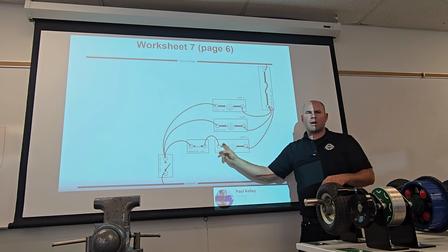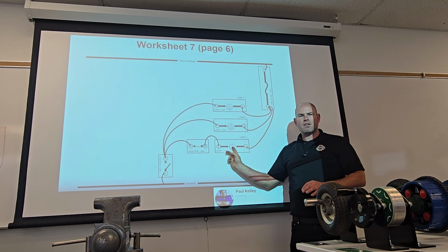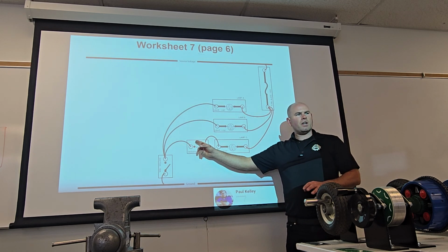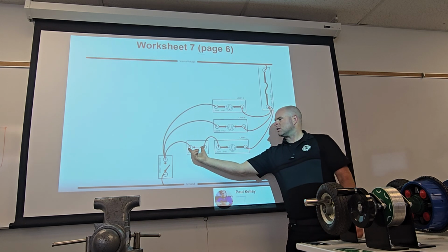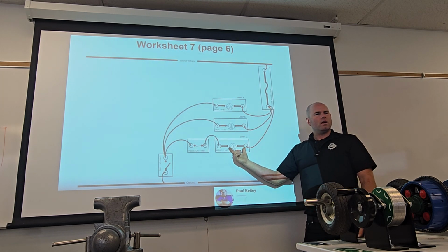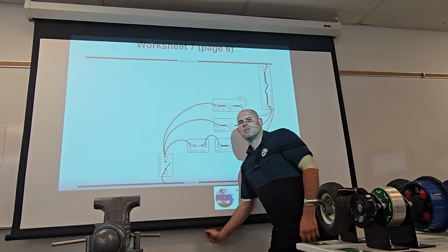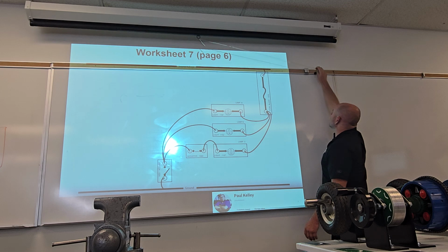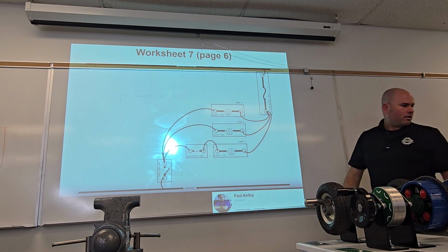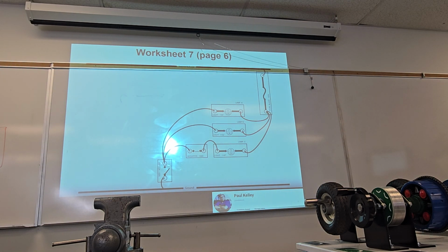but now that you see there's a load and another load, you know it's not going to drop the full 0. It's not going to drop everything. It's got to share. The question is, how much does it drop? And the answer to that is it depends on what the resistance is here versus what it is here. So let's make it simplified. I'm going to help you because I'm going to provide the resistance for you, which the customer would never do. So bear with me on this lesson.